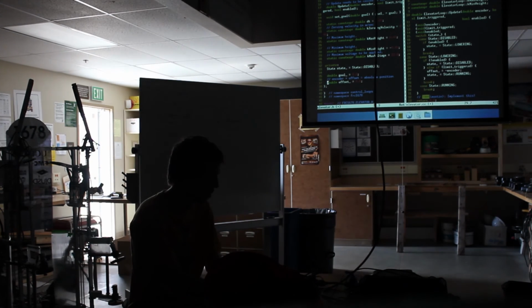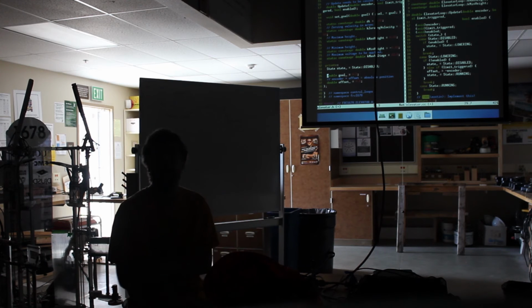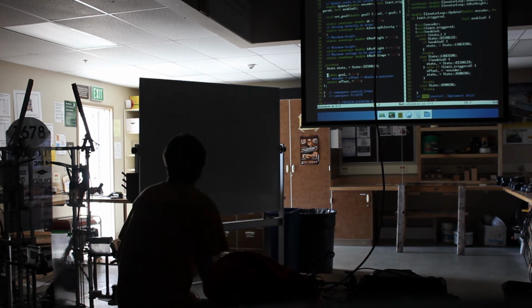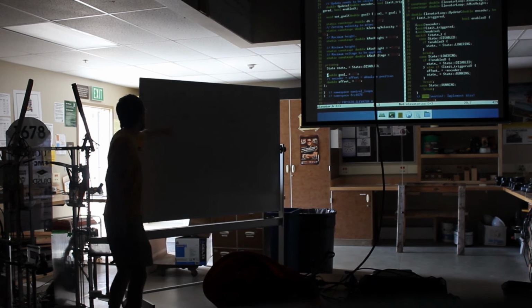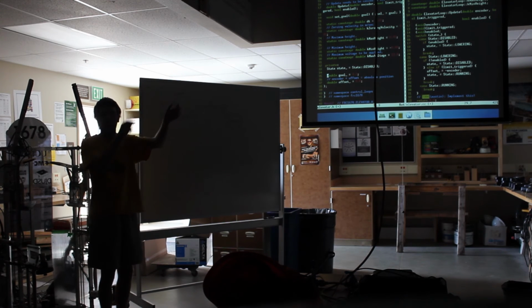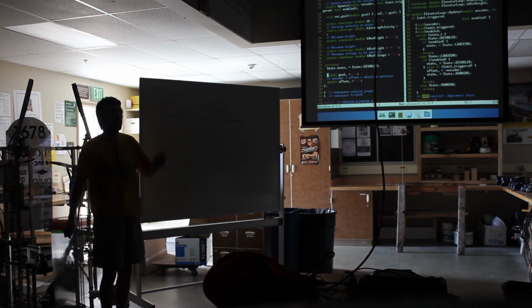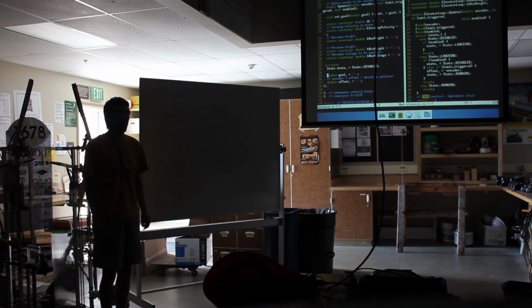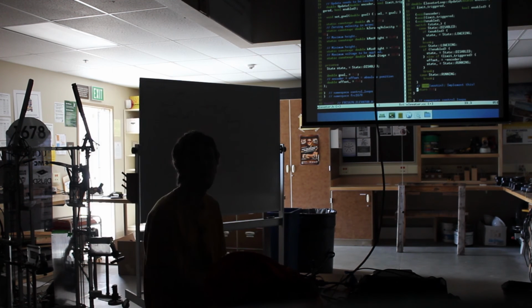So this is where the disabled state comes in. What we want to do is, when we're disabled, reset it to tell it to go where you started. And then every cycle, we want to move our goal down a little bit. When we feed that to our control loop, it will slowly execute this path we've given it. So it'll start at the top and then slowly move down in a very controlled manner until we get to the limit sensor, and then it will jump to wherever we asked it. Someone have a proposed way to do that?